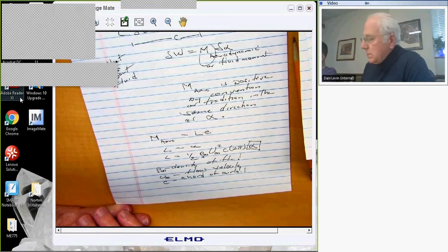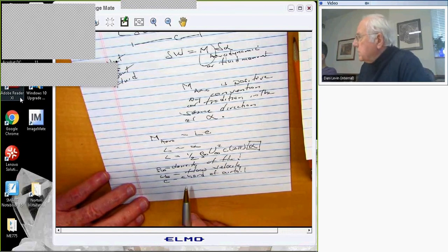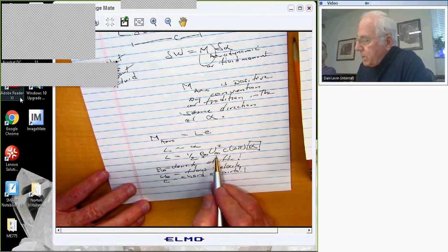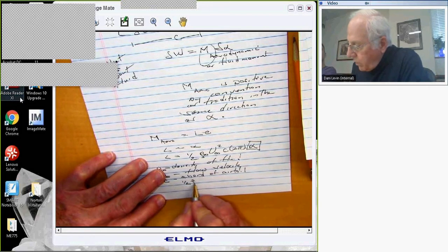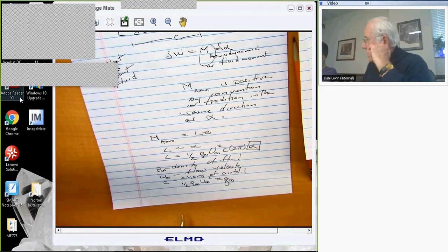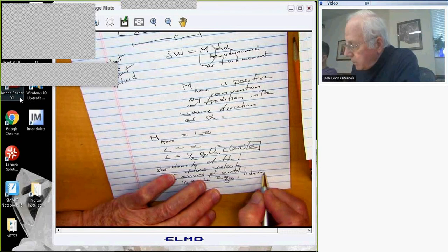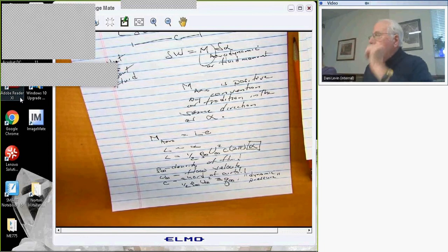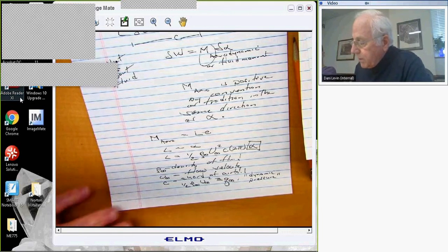So, rho infinity, u infinity squared has dimensions of pressure. And so, by tradition, this is called, misleadingly, dynamic pressure. So, 1/2 rho infinity, u infinity squared is often given the symbol Q, just so you don't have to keep writing all the symbols independently. And it's called dynamic pressure. Later on, when we talk about fluid dynamics more generally, we'll give some rationale for that name, although it's basically fairly misleading.